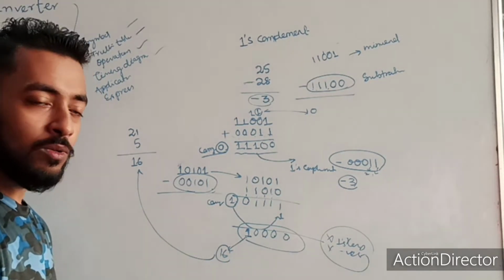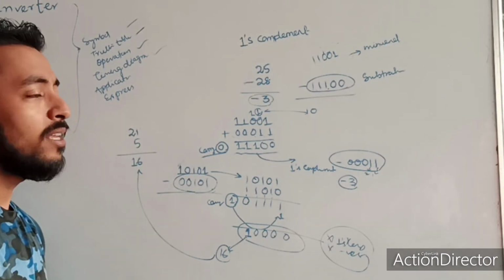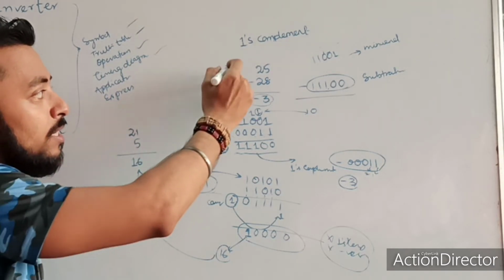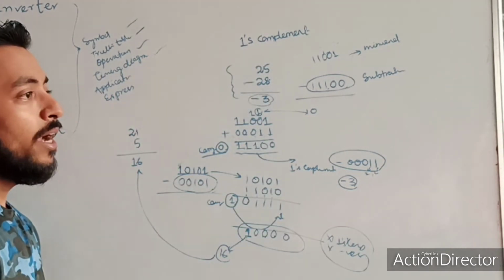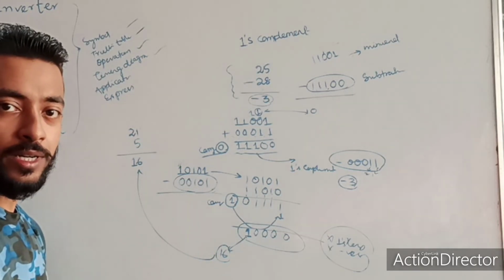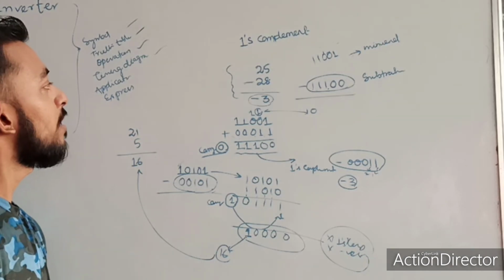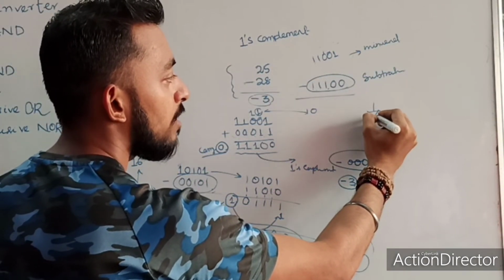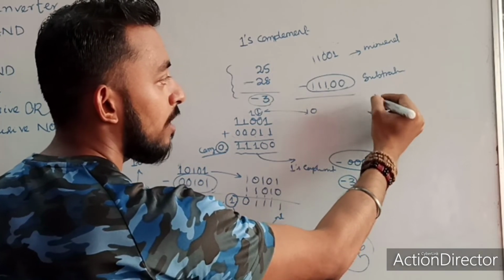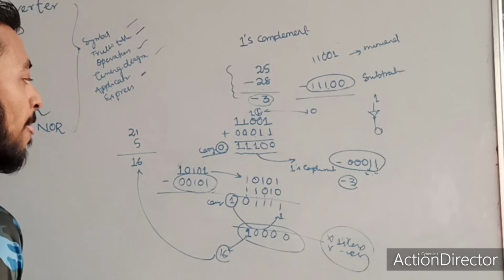Okay, so this is the use of 1s complement in binary arithmetic, that is in addition or subtraction. You can subtract a large number from a small number, and represent the sign component of a binary digit, that is the negative values of a binary digit. So this is the 1s complement. This is one application. The application is nothing but by just adding an inverter, whatever the value that is given, it will invert. Invert means it is nothing but the 1s complement.